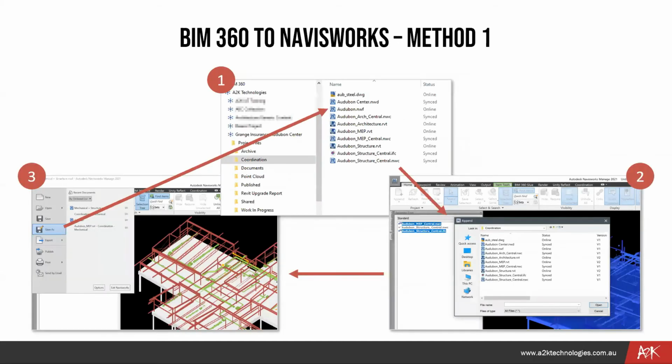If we have a look at method one, with Navisworks open on our desktop, we use the desktop connector to quite simply select files, probably most notably maybe NWC files, which are the cache files that we can generate from our design authoring tools like Revit, AutoCAD, Civil 3D, and so forth. And we can store those in BIM 360 so we can then simply append them as an aggregated or federated project file in Navisworks.